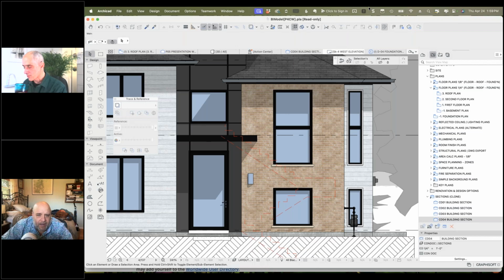To create that, I just hid the exterior wall layer in this view, and then with a polyline traced the stair profile. And then once the exterior wall was turned back on, we had that dashed reference showing where the structure of the stairs was. Okay, very cool. Yeah, it's a creative way to make sure it's exactly in the right place in relationship to this view, but it's a 2D element. Obviously, if the stair were moved or redesigned, you'd have to redo that again.